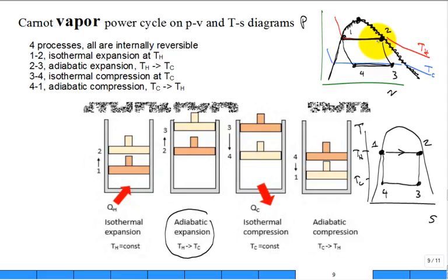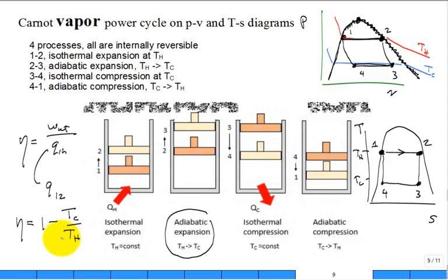If you're interested in calculating the thermal efficiency for this cycle, how would you calculate it? Well, you'd calculate the work net out and then Q in. Where is the Q in this cycle? Q, which process? Q in is only Q1 to 2, true? And if you actually go and check some pressures, temperatures, run some numbers, go in and out of the steam tables back and forth, you'll get a number. But if you then stop and compare it to this simple calculation, will you get the same answer?